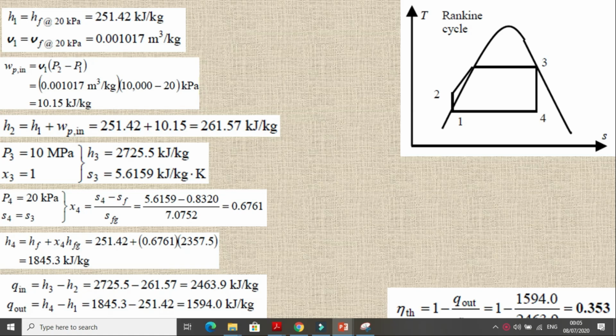Today we have discussed the Carnot cycle as well as the Rankine cycle, and we confirmed the increase in efficiency with the help of decreasing the condenser pressure, increasing the boiler pressure, or superheating. We also confirmed that the efficiency will increase.